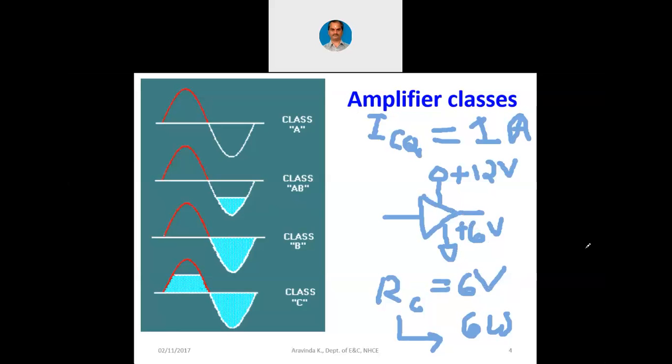So, across the transistor also 6 watts is there. Gradually the transistor will heat up because there is static power, and the life of the transistor will be reduced because of the continuous static power. That is why in such a case we have to use additional heat sinks, where the heat of the transistor is dissipated into the atmosphere and the transistor life can be somewhat increased.